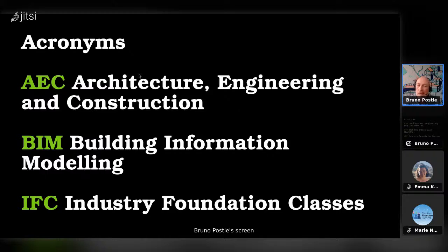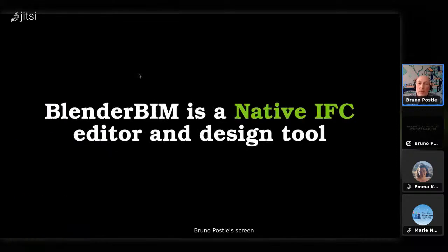Now there's one software standard for BIM, which is called IFC. IFC is an open standard. It's a text-based standard, and that supports everything that you might want to do with BIM in the AEC industry. Now, the great thing about BlenderBIM is it's a native IFC editor. All the other tools that use IFC, and it's basically all the tools in the industry, they either import and convert an IFC model into their own proprietary format, and then they export back to IFC. And what happens there is you get enormous amounts of data loss.